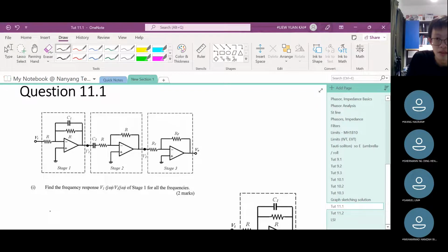Remember, when we look at op-amps, the three rules that you need to think of: V plus equals V minus, I plus equals I minus equals 0, and then just do KCL wherever possible. Not different from the last 2 weeks of our training. So looking at the op-amp system, there is something we can easily identify.